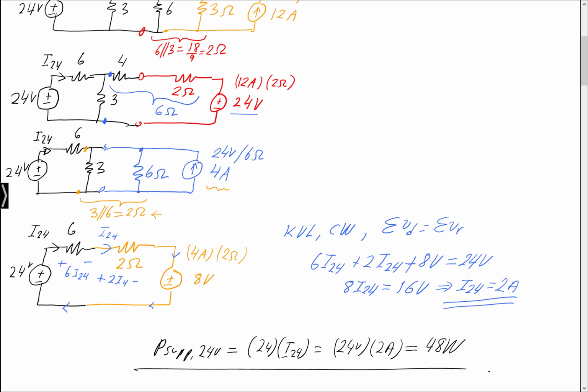So I hope you see that it's quite straightforward, and we really didn't write any equations. The only equation I wrote down was at the very end, a simple KVL equation. Everything else, when we're redrawing the circuit, we're actually doing the algebra. It's kind of equivalent to doing the algebra. So it's actually a good trade-off, because if you look, what kind of operations did I do? I did series resistance, parallel resistance. I did V over R to get an I, or I times R to get a V, for the sources. That's all I did. So it's a good trade-off if you think about it.